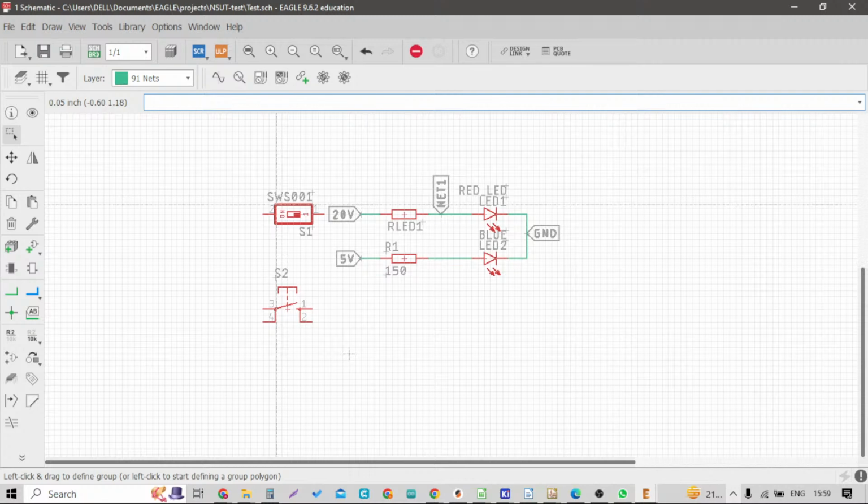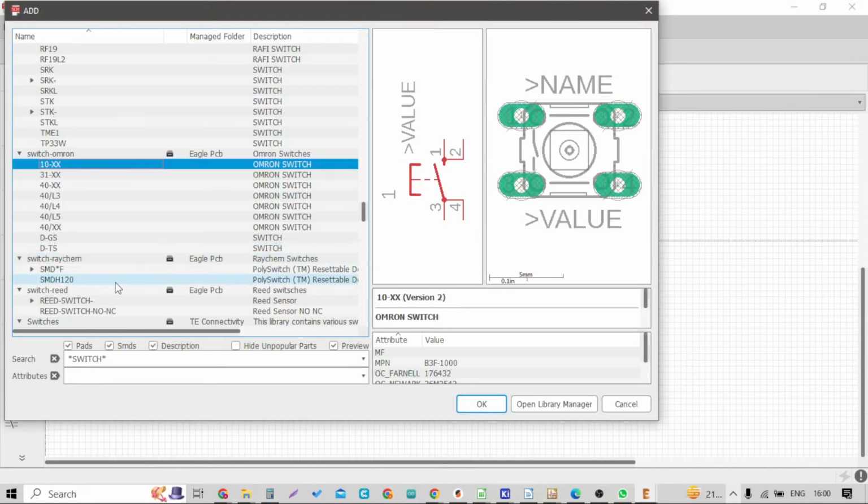Similarly, this electronic circuit will also require some power, so we can either provide a battery on this circuit itself, or if we want we can just use some kind of connector. Normally the kind of connector used in very basic electronics is the Molex connector, and we'll search for it using star M02 star.